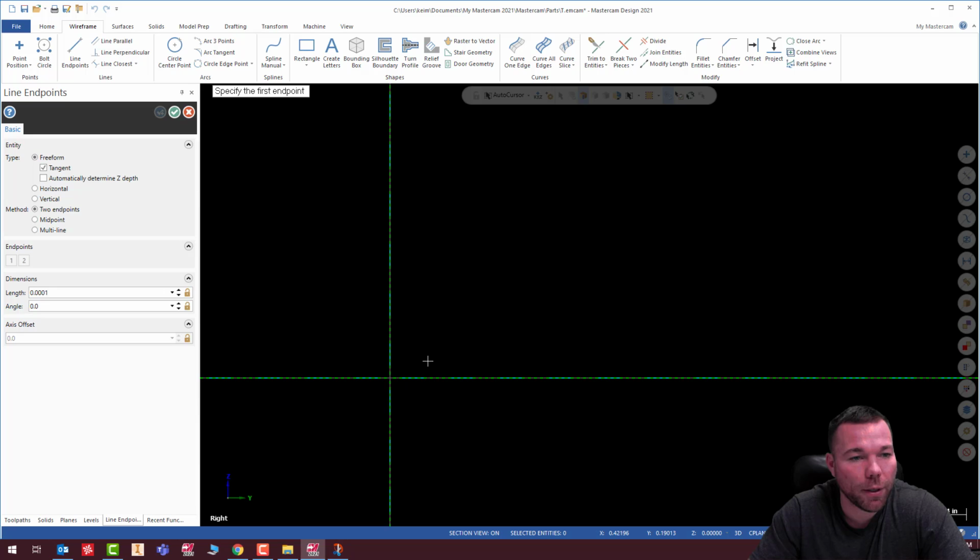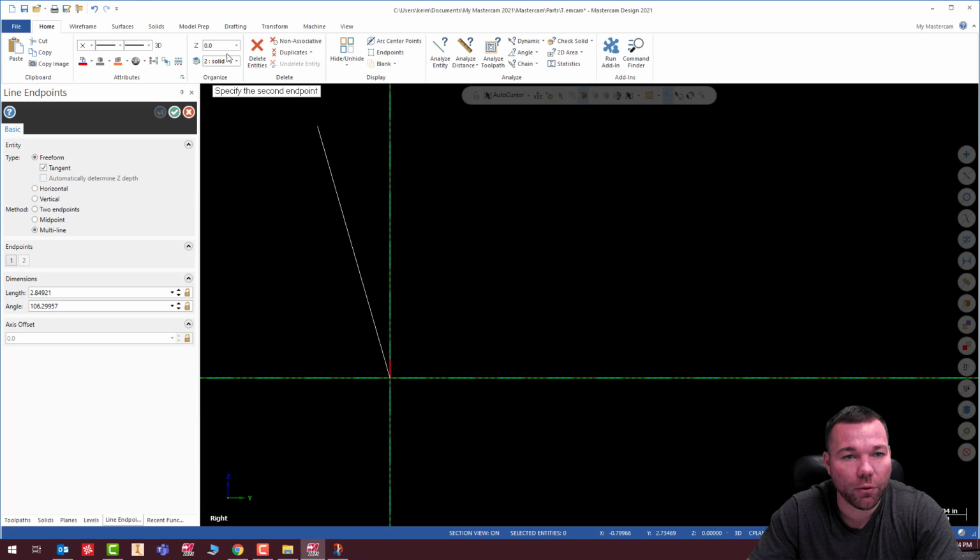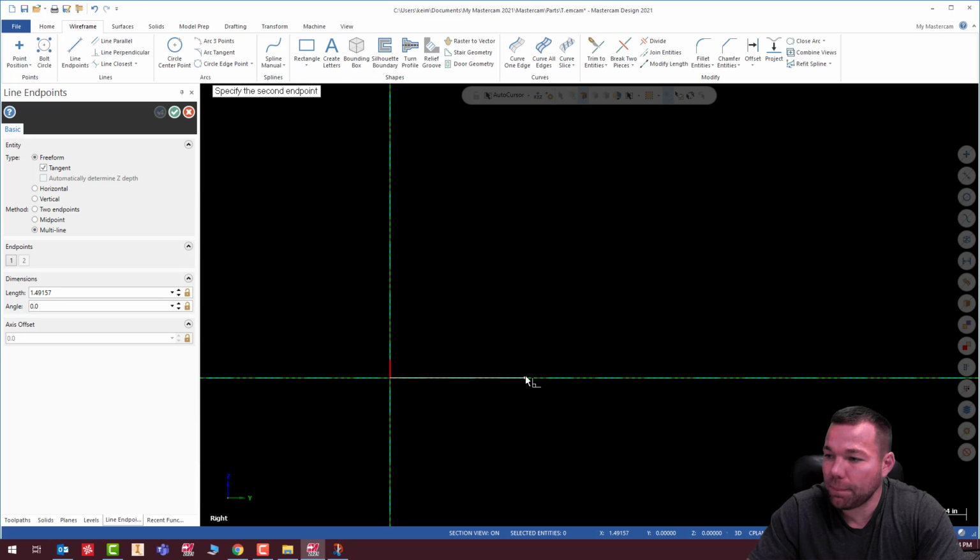So wireframe. And as always, I am doing this on the fly for these things. So I'm actually going to start in that 0.2 corner. I'm going to start at 0, 0.2, enter. And I'm going to come down to 0, 0. I just want to make sure my 0 is 0. Okay, good. And this is a 2.5 y, so I'm going to do 2.5, comma 0. And then I'm going to go to 2.5, comma 0.2. And that's going to give me that bottom section there.